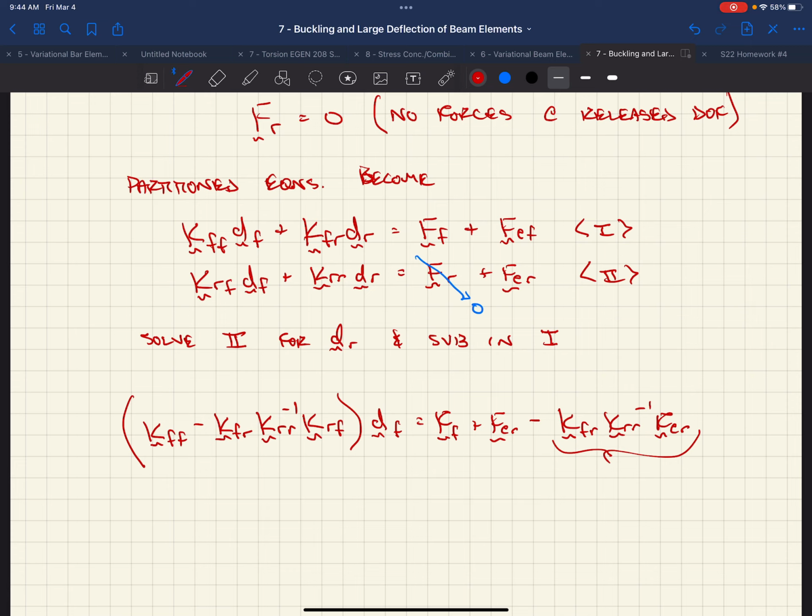So what do we end up doing? Well, we end up modifying our energy equivalent loads, right? So these are the loads. We know that you can't actually have nodal forces with respect to released degrees of freedom, right? If we say there's no moment transfer, we can't have M1 or M2, right? Depending on what we released. Similarly, now, like you guys are doing in the homework, you have these energy equivalent forces, right? Those are forces that are happening out in the field of our element. Our element doesn't care what's happening out in the field, right? It only cares about what's happening at the nodes. So we have to take those field functions, or field loadings, and equate them back into nodal loadings.